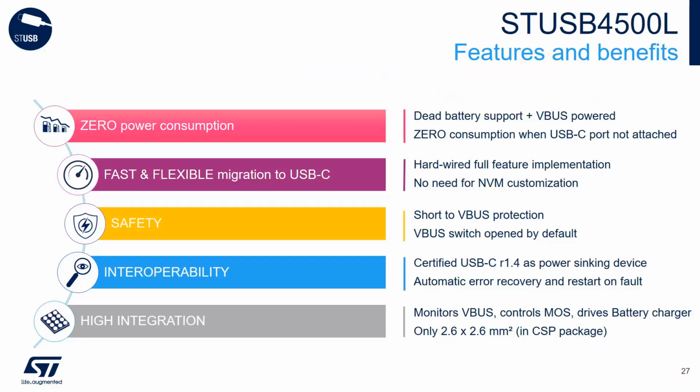What the ST-USB 4500L brings to your design. The main values are safety and interoperability, which are a must today as USB-C is being largely adopted. A benefit of the ST controller is that it's powered from the USB-C cable and only active when the cable is plugged in, so it enables zero power consumption, which is key for battery-powered devices. Then, because the product is standalone, implementation is straightforward, which is useful for mass-market applications. And also please note the availability of both chip-scale package as well as QFN package types.